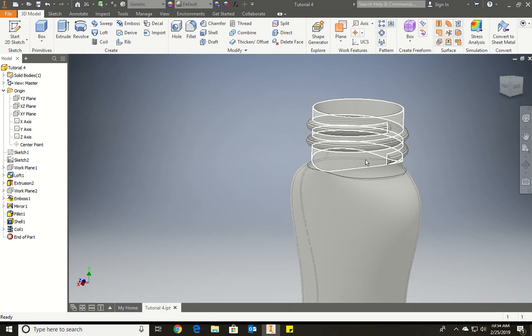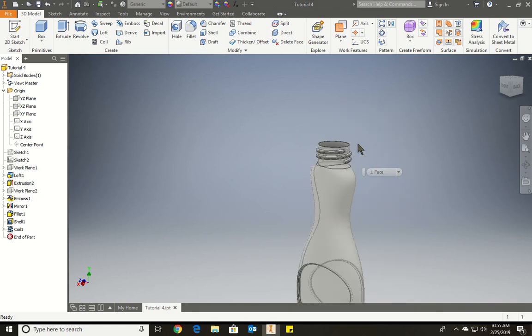Do we understand what happened before, why it wasn't working? It's because my line was thinking it was a center line, so it wouldn't use it. It wasn't completing the actual piece. So now that's done, we're going to press OK. And we have our lovely profile.